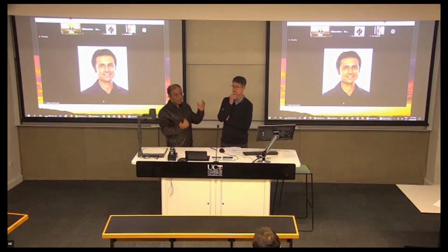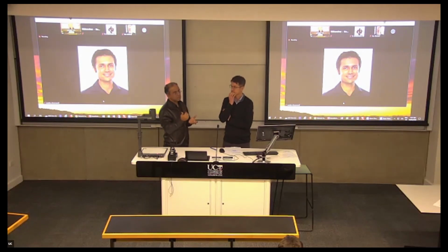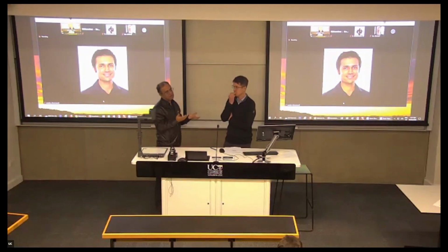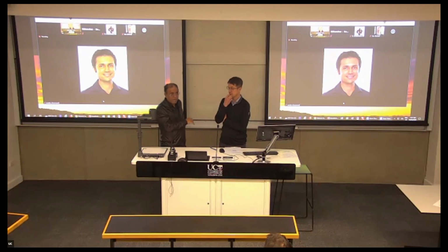I was involved in a comparative study between Japan, New Zealand, Europe, and the US. For the same design parameters and the same design demand, we were doing the design and detailing. Professor Park was leading the New Zealand team, and I was in Japan as a PhD student. I have the report: New Zealand is the weakest and most ductile for the same scenario. Maybe that is the reason why it is more of a problem in New Zealand. We noticed that when we compared building performance with Japan in the Kumamoto earthquake, because ours are much softer and ductile compared to the stiff and strong buildings in Japan.